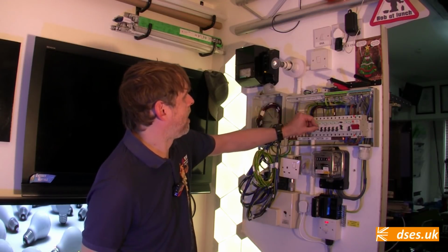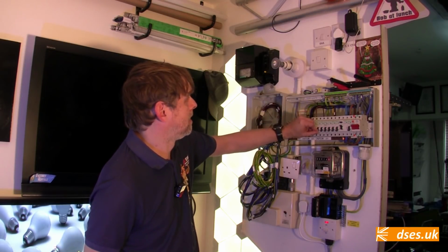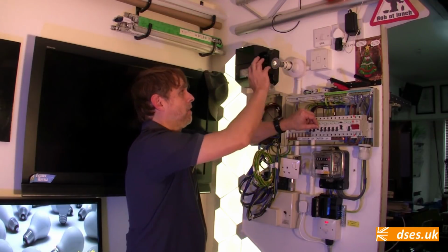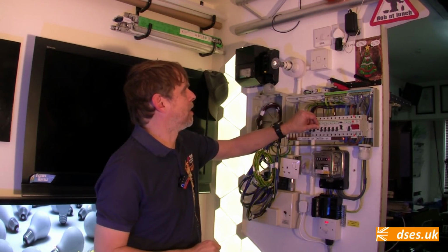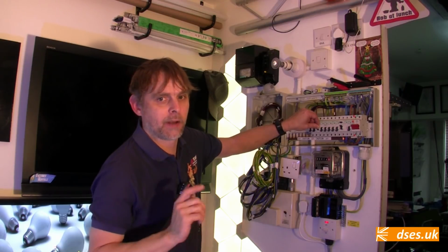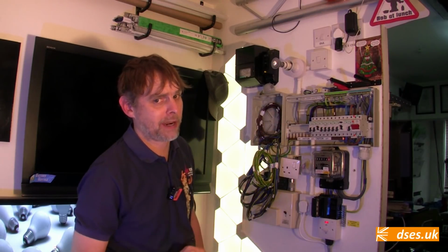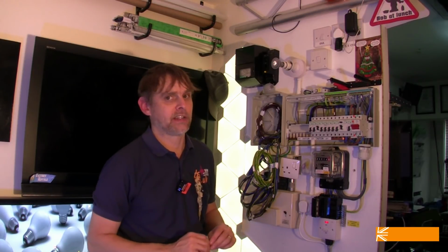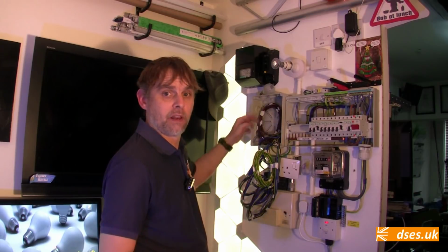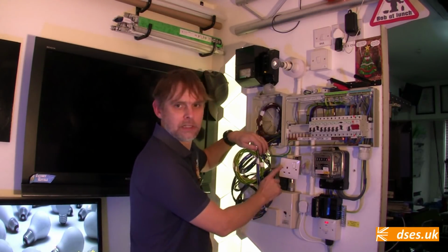And we've seen that when I energise that socket circuit, it has an effect on the light. The light is illuminating with a bit of a nuisance glow, a glow that should not be there. And I bet you're thinking it's something to do with electromagnetism, huh? After all, we all know that a current travelling down a wire creates a magnetic field. Only there is no current.